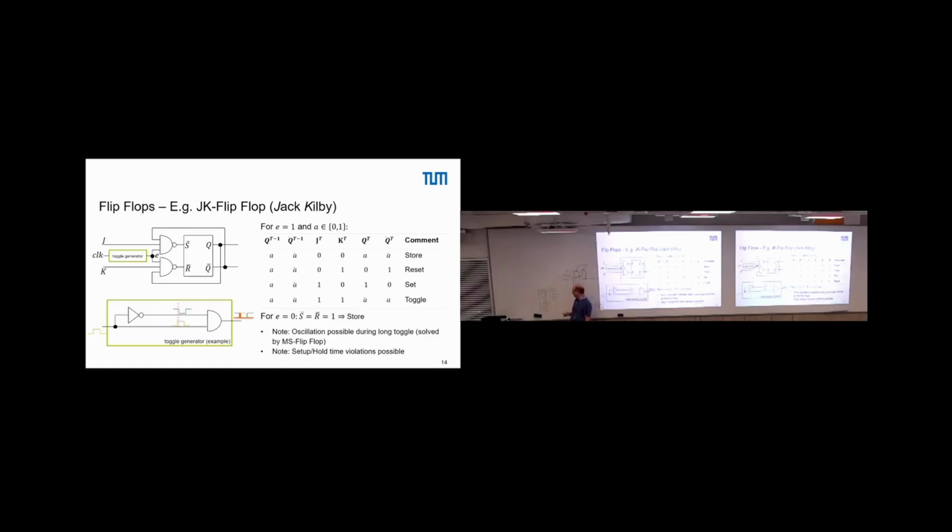So we need a pull up. This here was before a 1, should stay a 1. This here was before a 1 and should stay a 1. This here was before a 1 and should stay a 1. This was a 0 and should stay a 0, right? So in brackets is actually the NAND gate, 1, 1, 1, 0, 1, 1, 1, 0 with 2 inputs for A and B. And the other one is the actual output that we want to have. Right? So what do we need to add effectively?